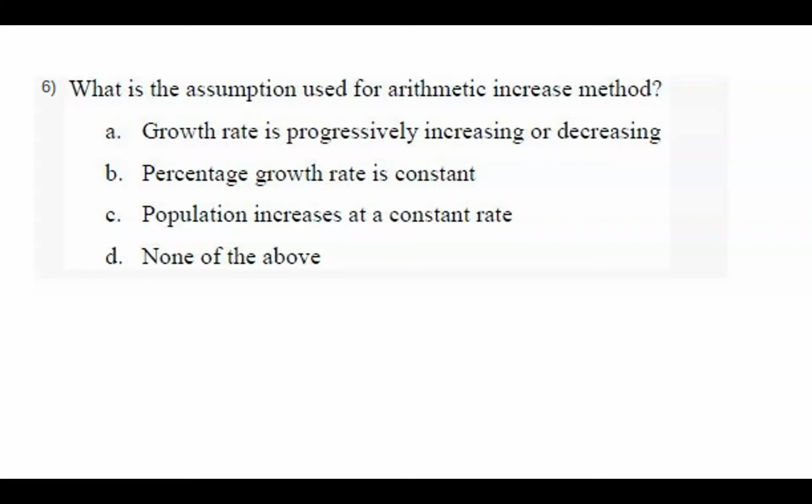So what type of cities do you apply this method to? Yes, right. Large cities. If you apply this particular method to small cities, or cities at the initiation stage, then it will predict a lower number of people in future compared to the actual value. It will underestimate the calculation. Okay, this method is clear, I guess. Then we go to the next method.